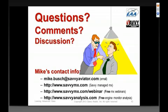But if you simply keep the CHT target in mind, everything becomes very, very simple. You don't have to worry about anything except, is my CHT too high? If it's too high, you've got to do something. If it's not too high, then you're good to go. That's why I really like using CHT as a leaning reference, because it's just so simple.